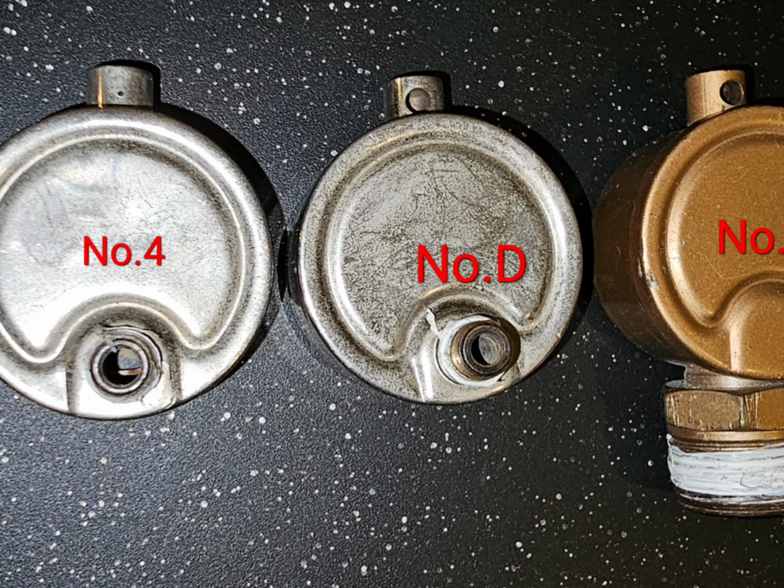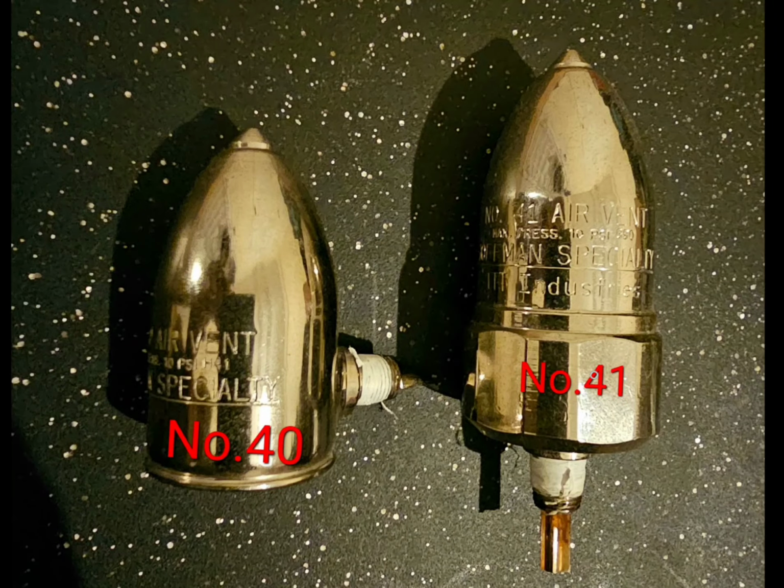And also just what I'm describing to you, if you look at that video that I showcased to you, it had a Hoffman number 41. That was the air vent I used on that radiator. This actually is a little bit larger. The 41 is slightly larger than the number 40. The number 40 is what you would find sitting on a self-standing cast iron radiator. The number 41, you would typically find these on steel convectors or cast iron convectors. Now the opening is slightly larger, which would mean it actually has the means to carry just a bit more steam capacity or momentum inside of the body of the valve.